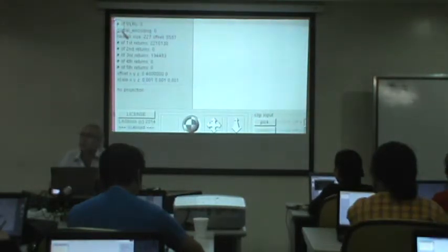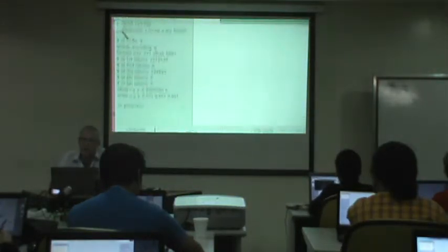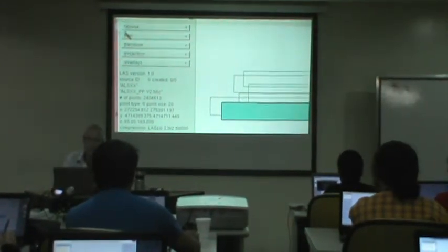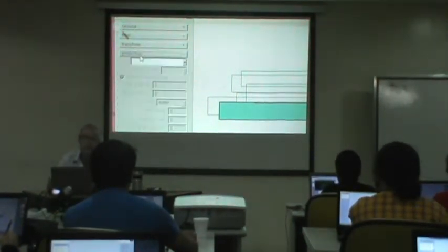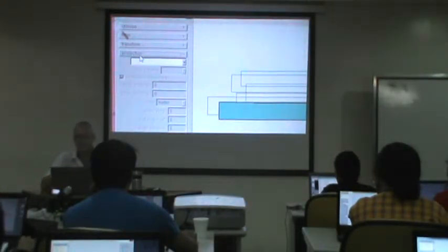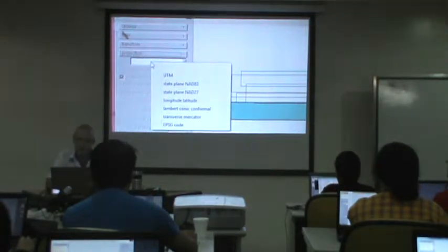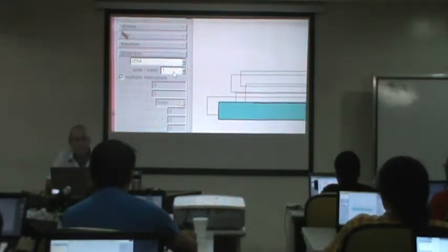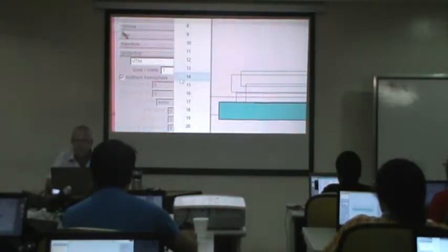I happen to know the projection for this, and we can edit again on the fly by using this projection tab. So now we use filter, we use transform, now we're using projection. Projection can add a projection that you know is missing, or you can override one that is wrong. And I know this is a UTM projection, it is on the northern hemisphere, and it's in the zone number...